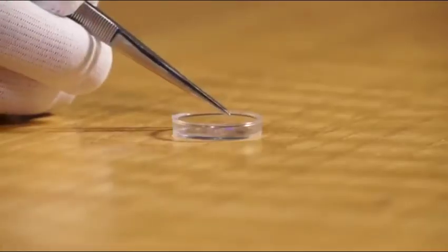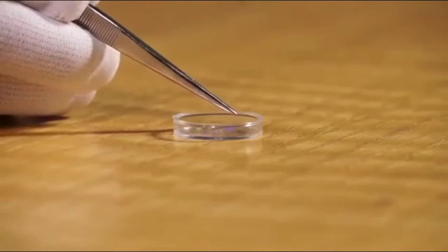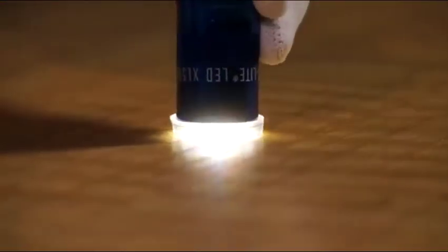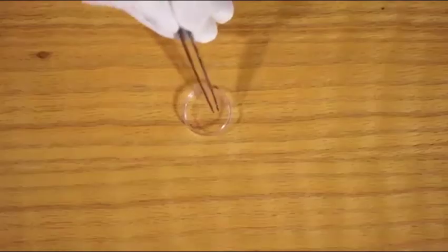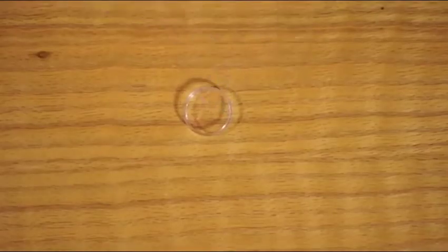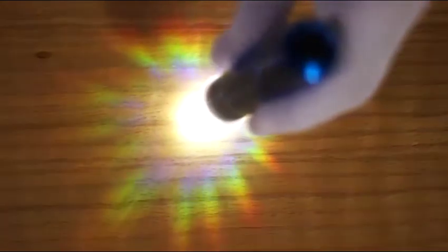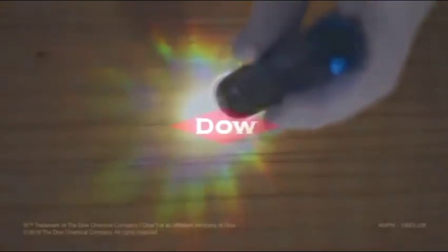Another benefit demonstrated with these silicone flashlight end caps is the design flexibility. The part snaps over the end of the flashlight's hood because of a bead that's molded on the inside of the cap. This provides tension, allowing the part to snap fit onto the hood. It also provides sealing benefits to keep dirt, abrasions, and the elements away from the flashlight lens.